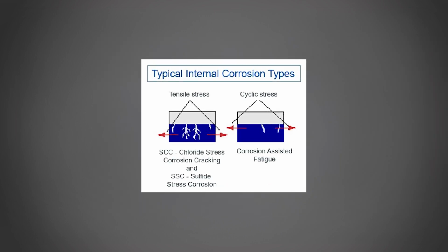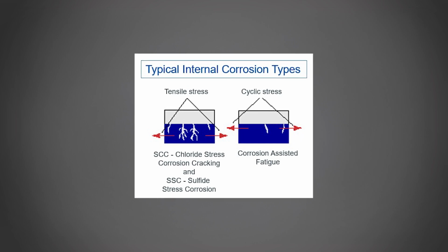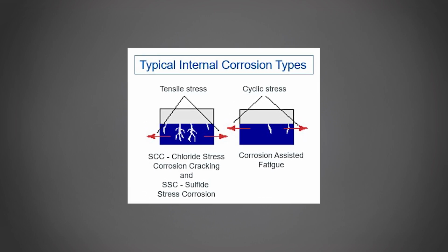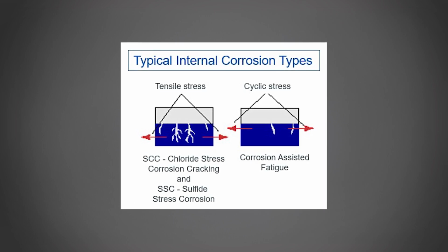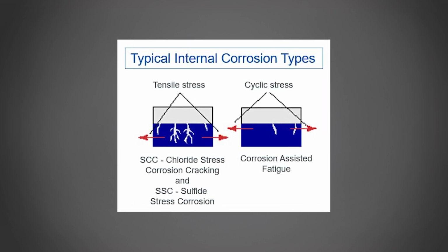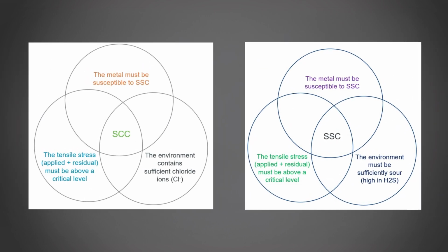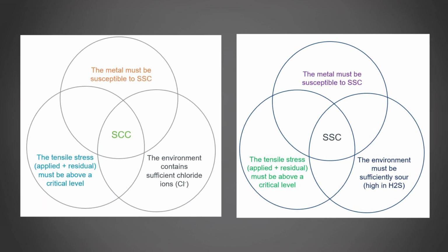From the inside, you've got hydrogen sulfide, which is a corrosive. You've got chloride ions, usually have a low pH or an acidic solution. And those things act together to have a corrosive attack on the material. And in addition to that, you have to contain the pressure. And so stress resulting from pressure containment can act in conjunction with the corrosion process to create damage.